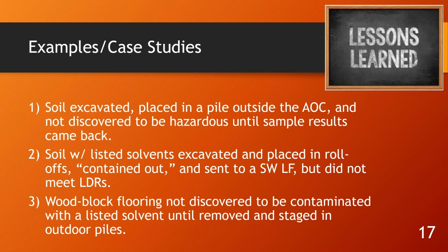And for the contained out determination, there are even now a lot of states that will say, even though it's not a listed hazardous waste, our facility requires a contained out determination. As time goes on, I get more and more of those requests. Even though it technically isn't listed, we still want you to go through the process of saying, we agree that it's below a certain remediation standard and that it can be, say, landfilled.